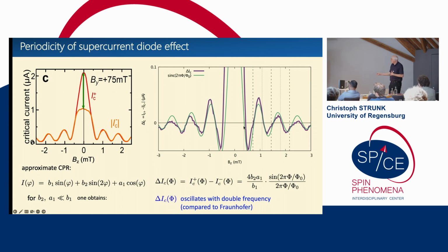That is precisely why the effect has to go through zero and vanishes. At this point, the two curves cross. Here red is underneath, red is above, red is underneath. These are the oscillations that you see. The green line is just the maximum of this current phase relation. So we understand this effect very well: it is really dominated by the second harmonic of the Josephson current.